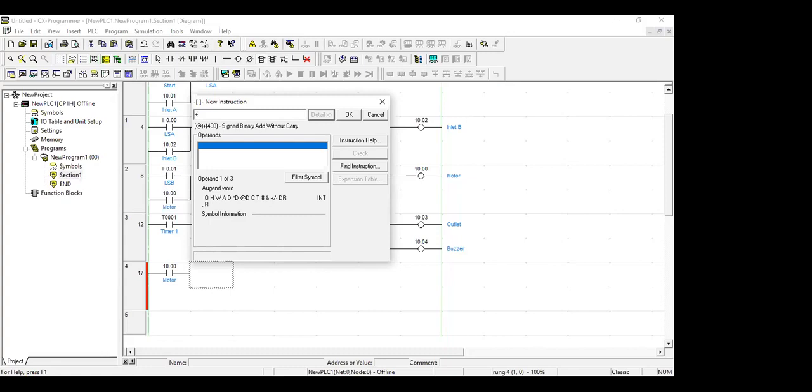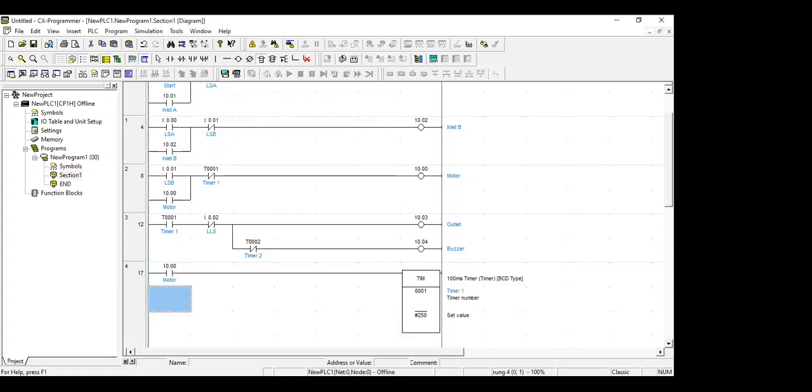Plus there. So you have many different functions. So we want the timer. See, it has 10. So now we want timer. So we press TIM. Then we go to the blue section that is here. Click on that. And it's timer number 1 we want. Now what is not obvious is that we need to put in the time. We have to click below that. There are other ways of doing it, but I will put in number sign and 250. I press OK. And then we see that the timer goes in.